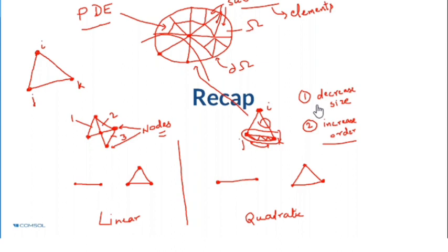But behind it, the solutions are obtained only at these nodes. So in the middle portion of these elements, the solution is obtained via interpolation. All those results are interpolated. Okay. Now to capture these interpolation functions, we also call them shape functions.